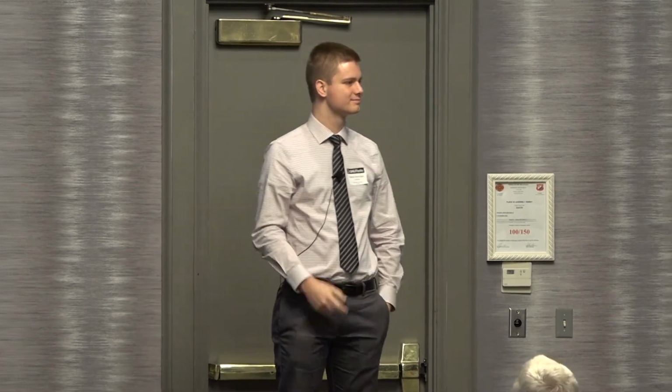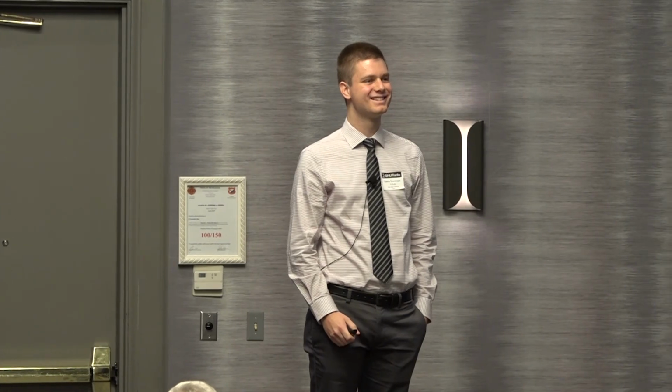Yeah, good answer, thanks. My question is, what are the modulation techniques and waveforms? Yeah, so in the proof of concept test we did, we just used exclusively a QPSK waveform. Yeah, this one I saw, but if this is your QPSK, you're dead. This one I can tell you, your error is incredibly big, and you will have problems.